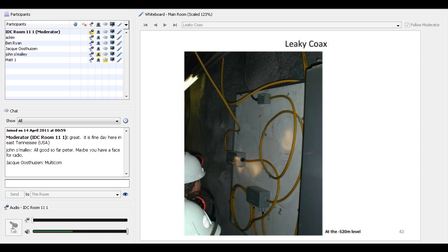In case you're wondering what these little boxes here are, Peter? Amplifiers. They're repeater stations. The signal is degrading in amplitude because it's leaking out of the cable. It's leaky coax. So every so often, you jack it up again with one of these amplifiers. It's a pretty interesting way to build a distributed antenna, a leaky coax, for your radio system.